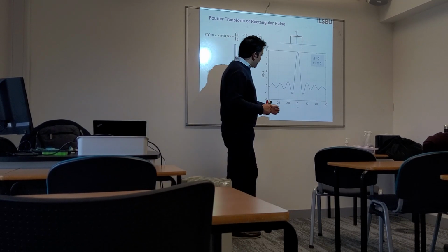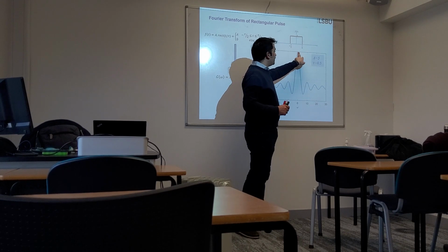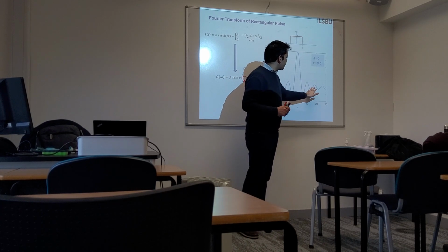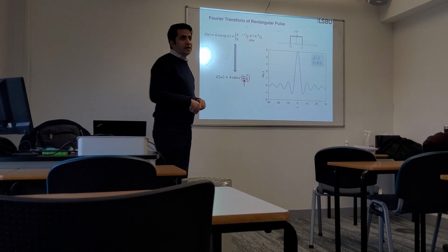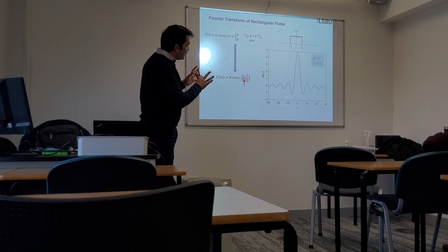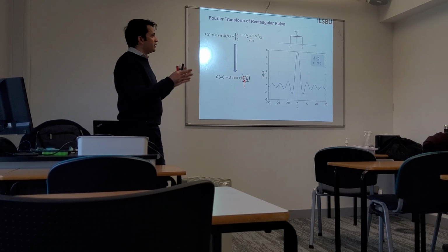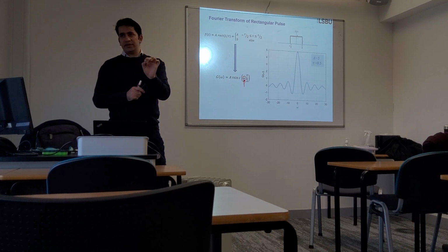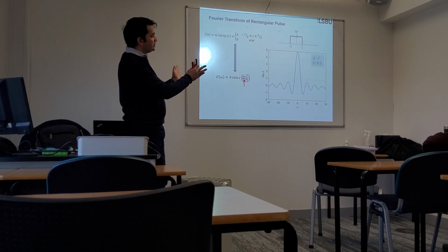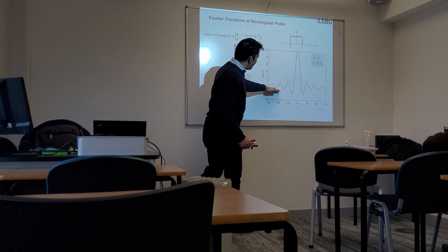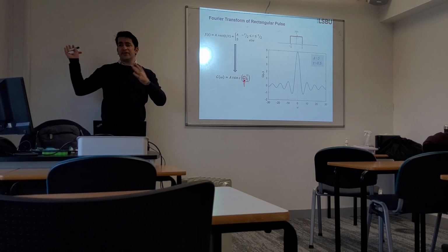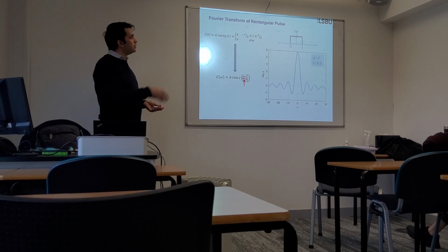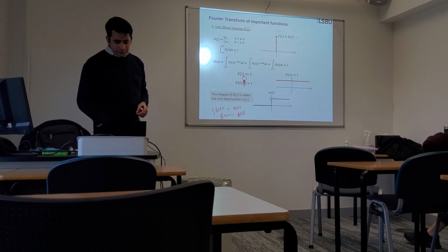You can see that it has a DC value, which is at 0 frequency, and at DC this is maximum. If we go towards positive frequency, you can see how this is responding. So in the frequency domain, this signal has a big magnitude at 0 frequency. However, we do have magnitudes at other frequencies, but as the frequencies go towards infinity or towards a higher number, their magnitudes go down. So this is how we analyze a time domain signal in the frequency domain.